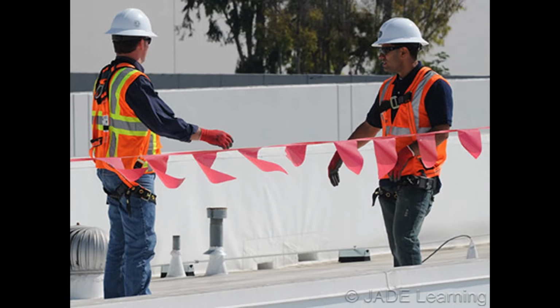Protection from falling objects. Employees potentially exposed to injury from falling objects are required to wear a hard hat and shall be protected by the following measures, designed and installed per OSHA 1926.502 as determined by the competent person. Erect toe boards, screens, or guardrail systems to prevent objects from falling from higher levels. Erect a canopy structure and keep potential falling objects far enough from the edge of the higher level so that those objects would not go over the edge if they were accidentally displaced.